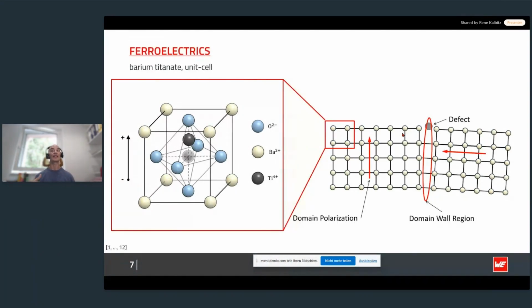The ferroelectric attempts to attain a domain configuration that minimizes the total energy while satisfying both electrostatic and mechanical boundary conditions. In an idealized system, all the dipoles in the crystalline material would collectively point in one direction.